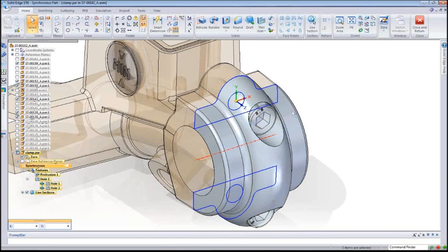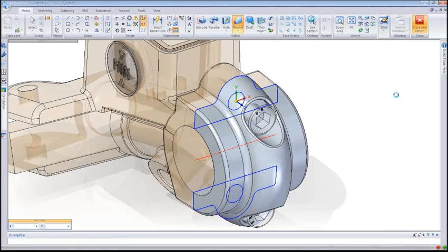That's cool. From here, I'm going to reach in here and do a quick round. This round, I wonder what size it is. Oh, yeah, it's way too big. So probably about a 0.5 millimeter round on there. And that looks great. And I forgot to do that one, so that looks awesome. And hit close return, because we're done with that little bit.